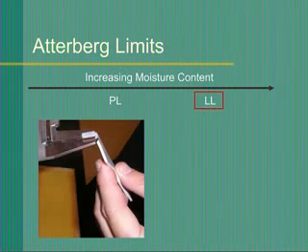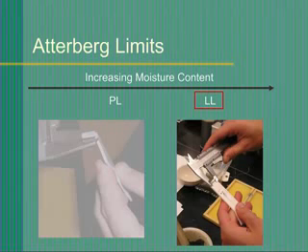First, check the grooving tool to ensure that it is clean and that the tip is not wider than 2.1 millimeters. While checking the grooving tool, note that the butt end of the tool has a calibrated tab that is 10 millimeters high and 13 millimeters wide.